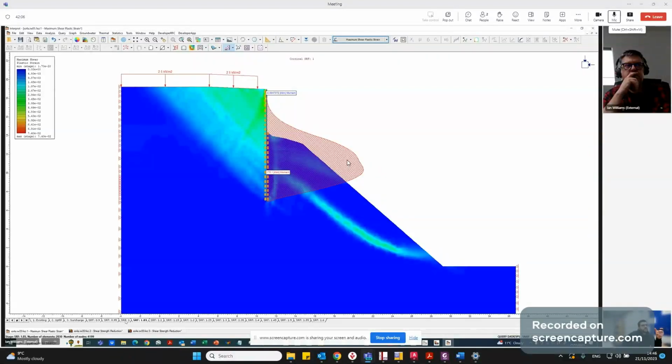So now in this situation, the wall has failed. So is this moment realistic? Well, the wall hasn't failed because the wall's elastic. The slip has. Yeah, the slope I think has failed. So in order for me to avoid this situation, does the wall need to be that strong, or is it enough to have the 150 that I had before? Well, personally, I think you probably need either a longer wall or a stiffer wall.